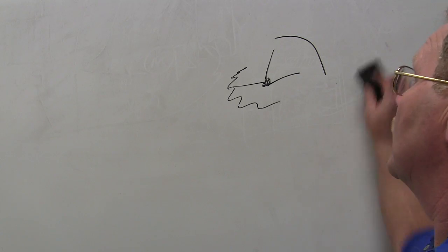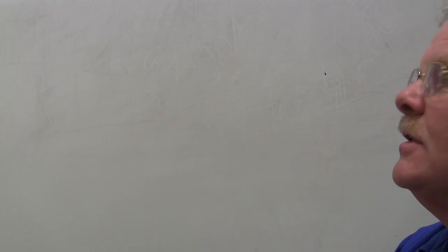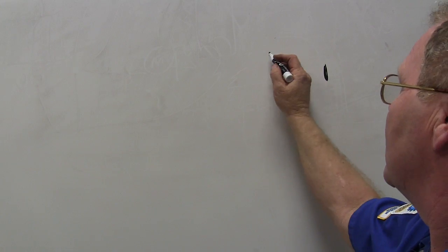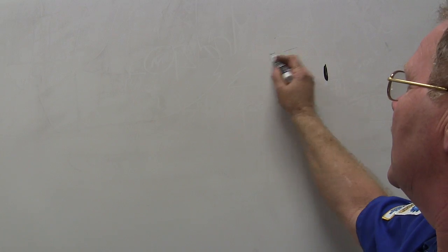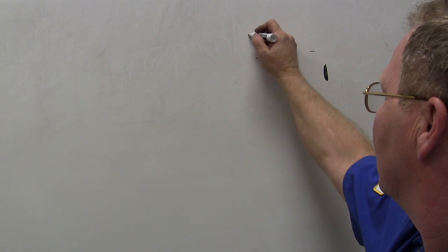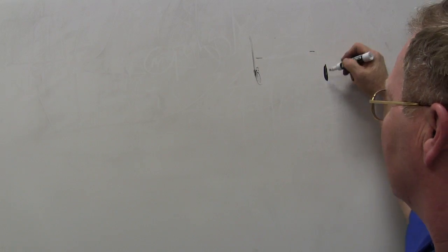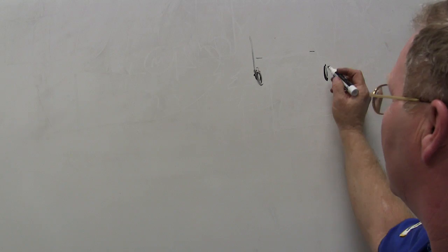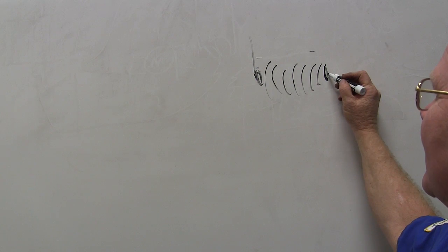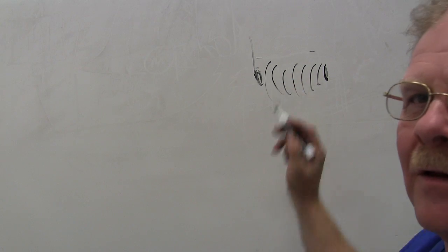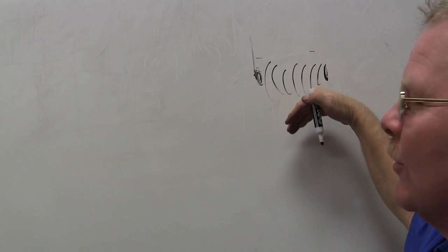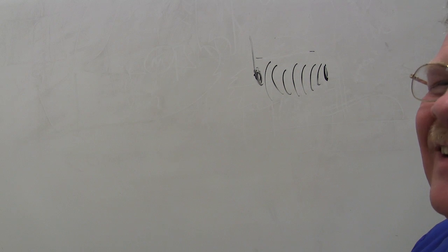What is a Karman vortex? Imagine this, and I've got one of those over somewhere. You've got airflow, and a sort of coarse honeycomb, so if you looked into it you'd be looking at a honeycomb. And the sensor has on each side of it sound waves. It's got a tiny speaker and a tiny listener, at a frequency you can't hear with your ear. As more air goes through there, it has a tendency to blow those sound waves away from the other. That's interesting, isn't it?